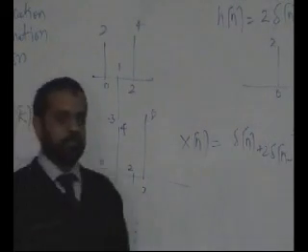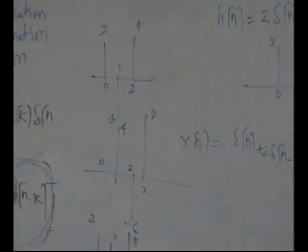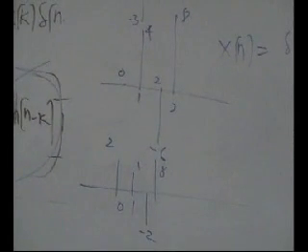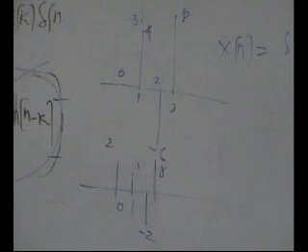So this is the answer. Just knowing the impulse response, you can compute the output of a system due to any signal, and that is why we always try to deal with linear and time invariant systems. It helps you to only need to worry about an impulse. If you worry about an impulse, then you are done. You have solved the problem.